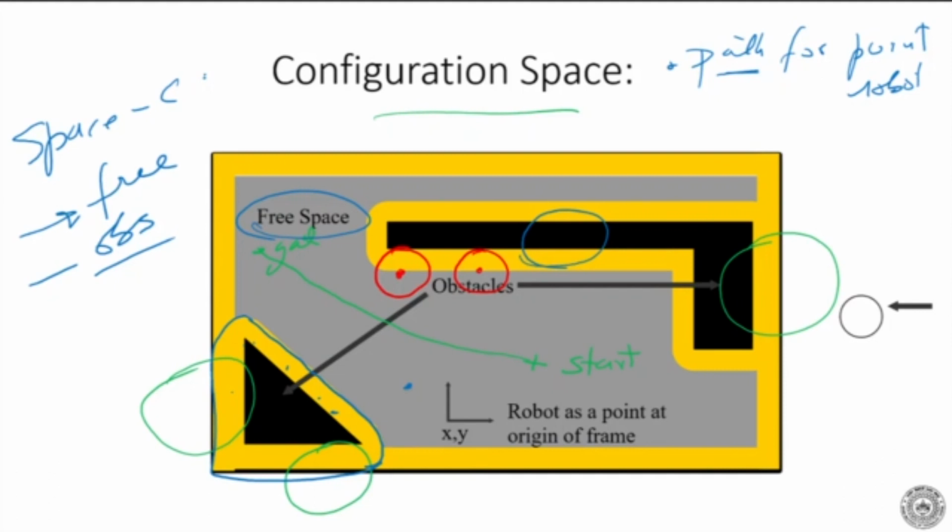So today we will stop here and then proceed. Now what I would suggest is that please draw a few sample Cartesian spaces and C spaces, and then for a mobile robot, please understand how we move from the Cartesian space to the C space, and also understand why we are doing this. It's very important to understand that path planning will be basically done for a point robot. Otherwise, if you're trying to plan for a circular robot, which is moving in different directions, you can imagine that.